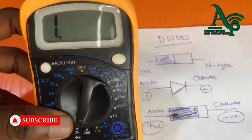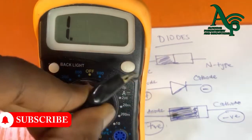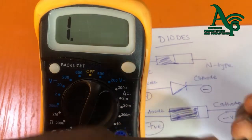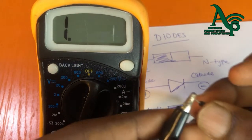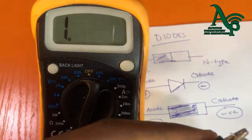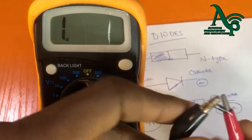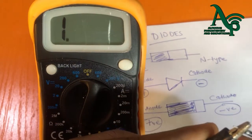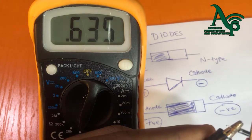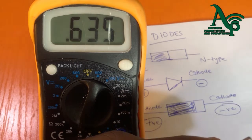Remember, the diode has two terminals, positive and negative, and this is the negative probe of our multimeter, and we're going to connect the negative probe of our multimeter to the negative terminal of our diode. We're going to connect the positive probe to the positive terminal of the diode. Now we will get a value on the screen of our multimeter. All right, we have our value on the screen of our multimeter now.